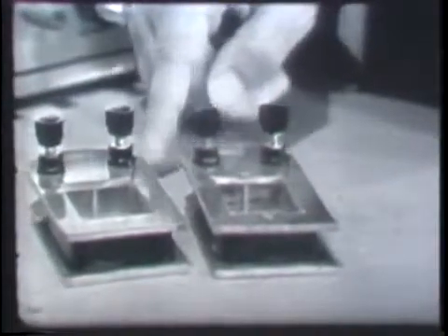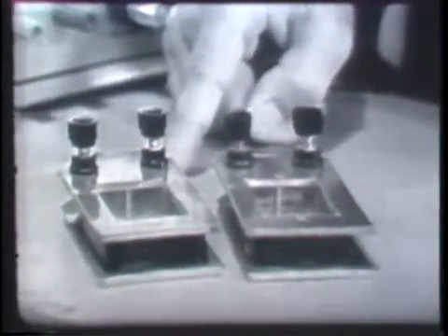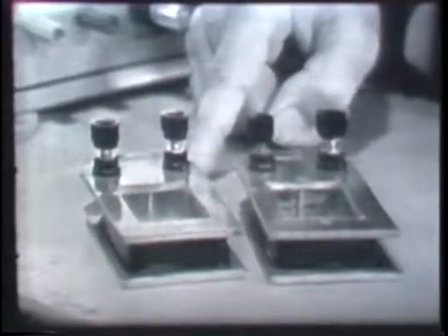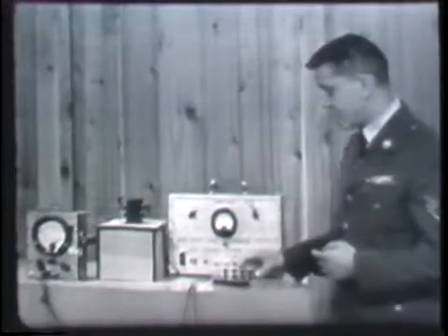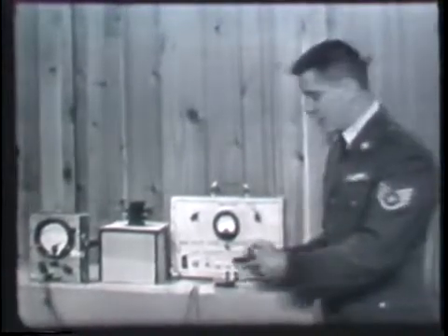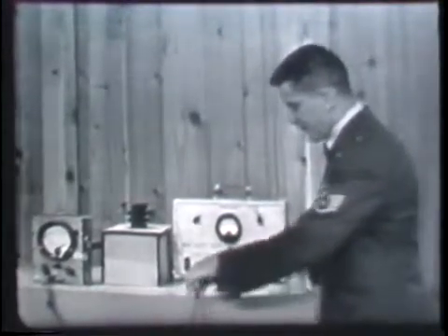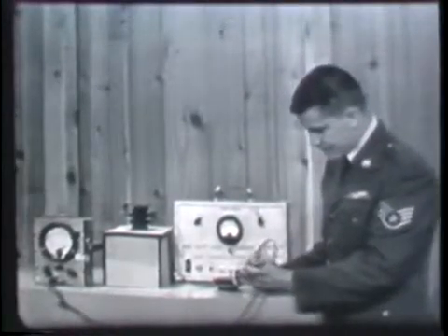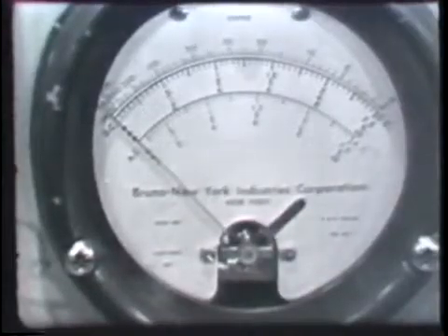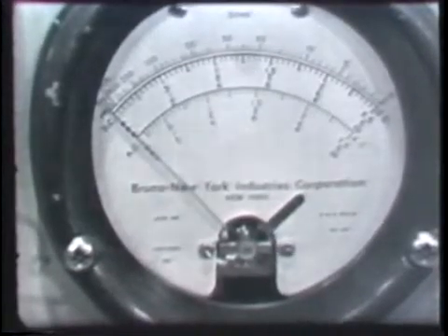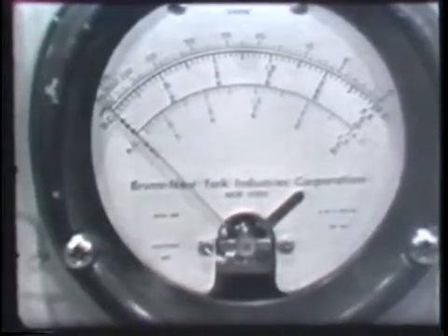The big difference in these two windings, however, is that one of them is shorted and one of them is open. So let's use our ohm meter and see if we can tell which is which. Now remember, the PSM6 has already been set up to read resistance on the ohms times 1 scale. So let's go ahead and check the resistance of the 150 turn winding first. If we'll take a look at the meter now, we'll see that it reads infinity.